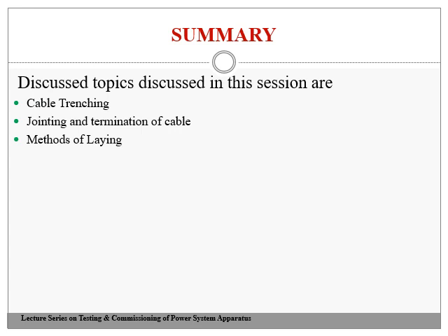Therefore, in this class we came to know about the meaning of trenching. The trenching method depends upon the number of cables to be laid down. The specification or the guidelines given by the manufacturer have to be followed. Then afterwards, there is jointing as well as termination. This completes today's session.